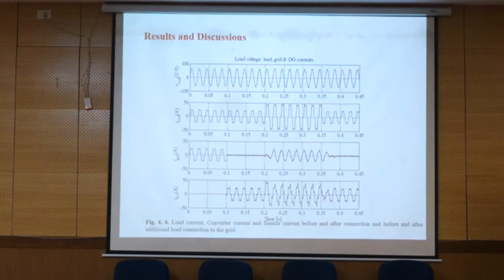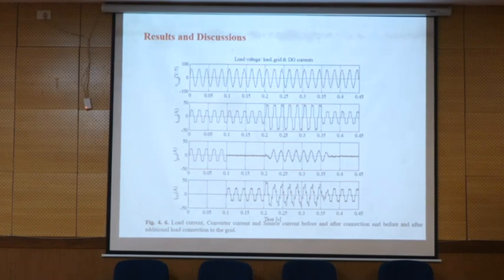So we inject maximum reactive power and harmonic, but if we have some available, it's like your load is 22, which 5 is harmonic in D axis, 5 is harmonic in Q axis, 5 is reactive power, and 7 is active power. But your converter just can provide 20.